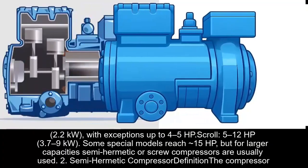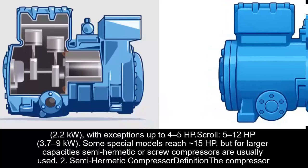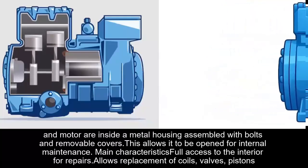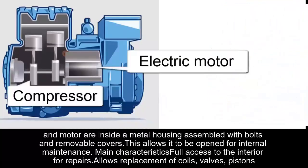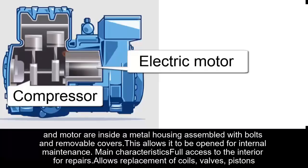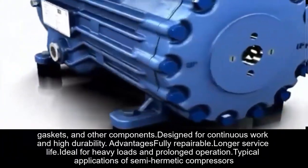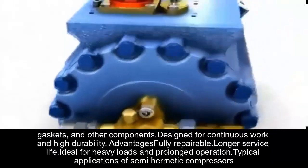2. Semi-hermetic compressor. Definition: the compressor and motor are inside a metal housing assembled with bolts and removable covers. This allows it to be opened for internal maintenance. Main characteristics: full access to the interior for repairs. Allows replacement of coils, valves, pistons, gaskets, and other components. Designed for continuous work and high durability.